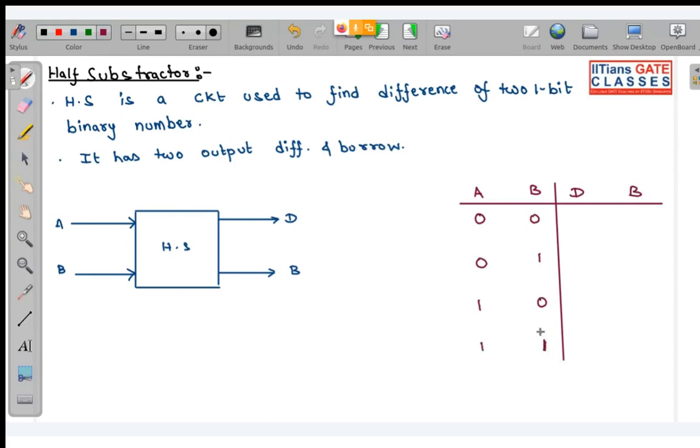Yes, if we want to solve like this 27 minus 36, I guess this we can solve using 9's complement or even 10's complement. Like 36 in 9's complement will be what? It will be 99 minus 36. So this will be 6 and this will be 3, that is 63. So this is 9's complement basically. So if we add now 27 and 63, what do we get? So this is 90 we are getting.